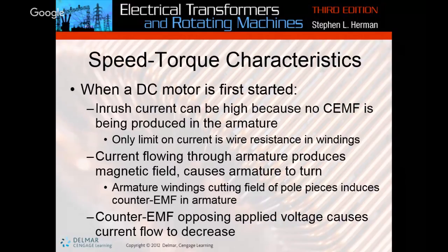Okay, and this is the case for sure in the DC motors on the big shovels that I worked on, and depending on how the actual field is wound and how it's wired, it should be pretty close to what's set up on most other applications as well, because we need that opposition to current flow to create that rotation.